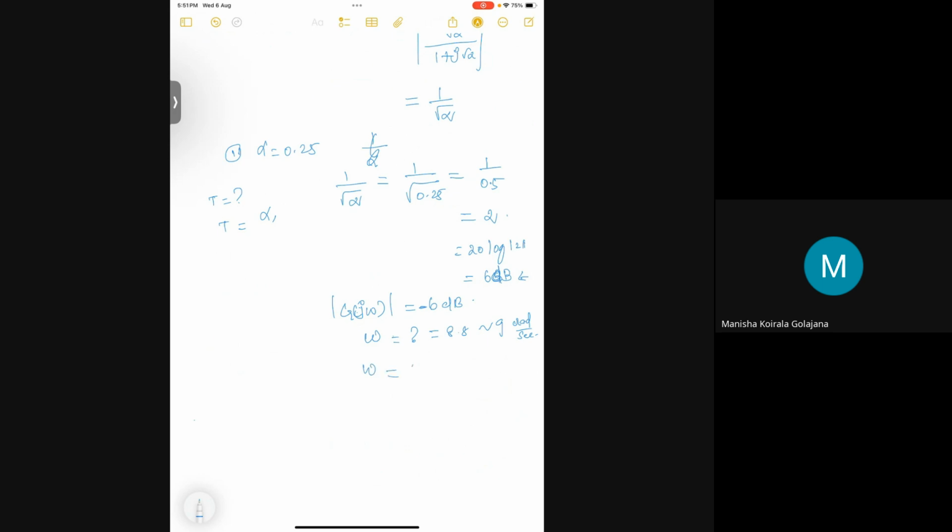So this omega becomes your new omega GC. Previously, how much was the gain crossover frequency? It was 6.15. Now we are choosing this omega GC as 9 because of the phase margin requirement. So we are finding this omega GC in terms of our alpha to compensate for our requirement, that is, greater than 50 degrees of phase margin.